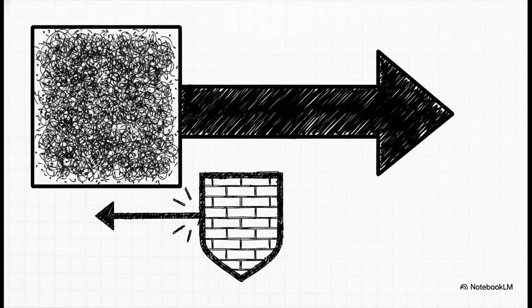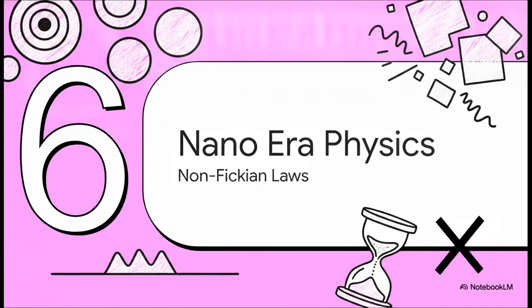Now, to perfect that second metric, the emitter injection efficiency, engineers rely on a really clever trick. They heavily dope the emitter with impurities to physically restrict any wasted reverse diffusion. By making the emitter vastly more concentrated than the base, they effectively manipulate the Fickian math to force a massive asymmetric forward injection. They basically stack the deck so the diffusion has absolutely no choice but to flow exactly where we want it to.